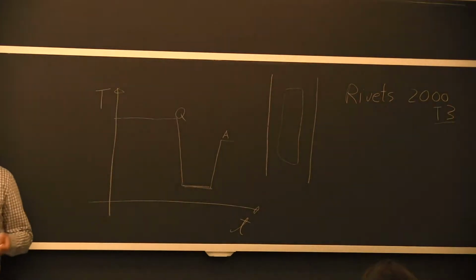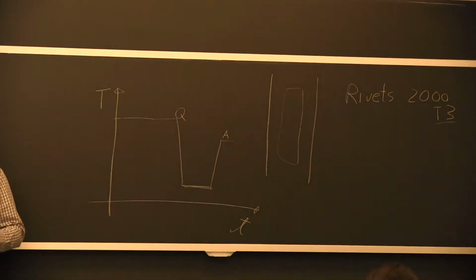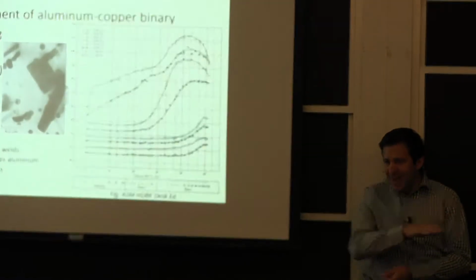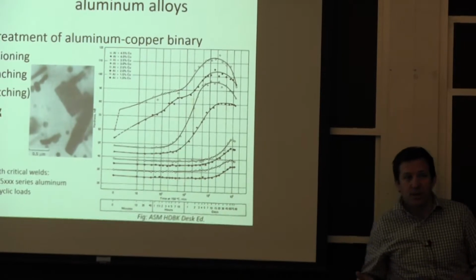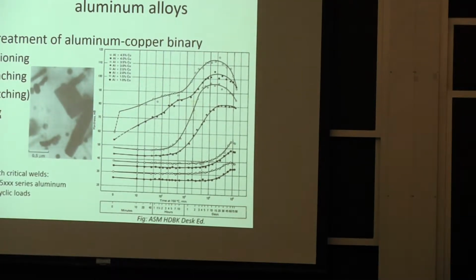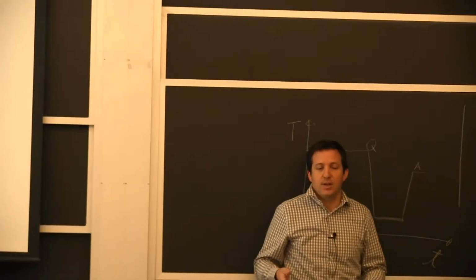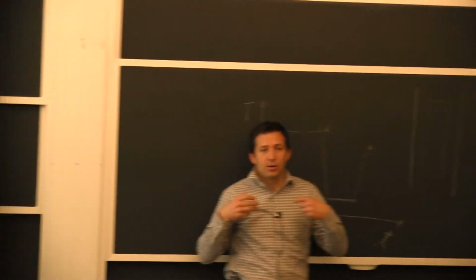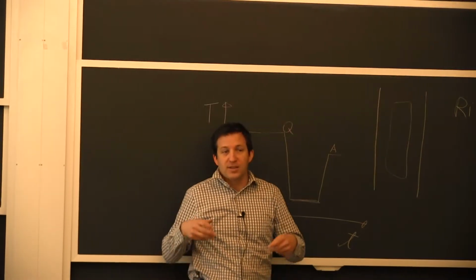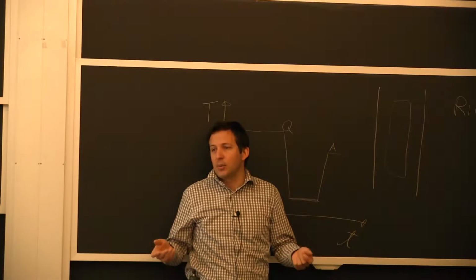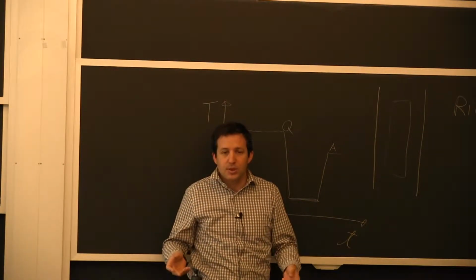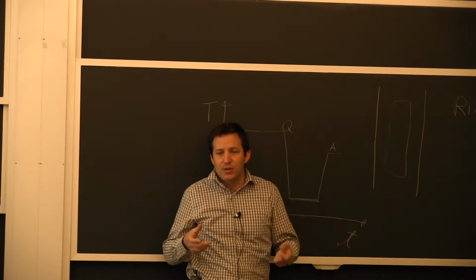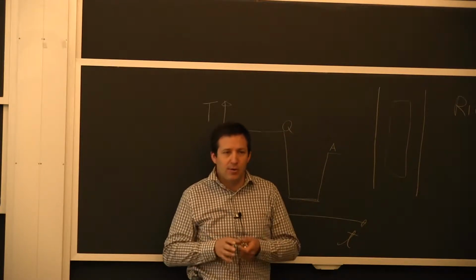A lot of them will be coherent, which means that you have a different composition, but your lattice, your crystal, is still continuous. It's deformed, but it's continuous. So what happens with something this small is dislocations can still go through it. It will provide some friction. It will increase the properties a little bit, but because the dislocation goes through it, it's only going to give you a limited amount of hardening.